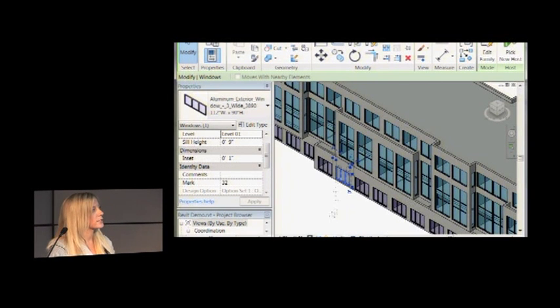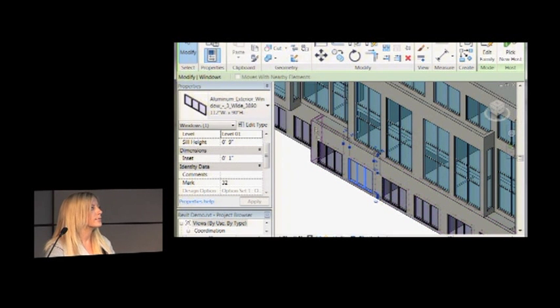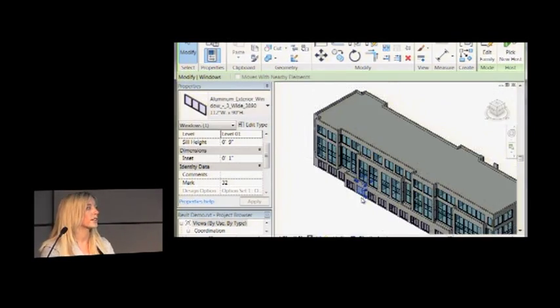But for those spaces, you basically just want to get rid of the room and make them external, because they're not actually an external space. They're a porch, they become a shading surface, or it's an atrium, and you don't need to have that defined as a room, because Revit will allow you to define it as a room, which is completely in opposition with the way that IES defines it. And for many of those openings, they sometimes will be filled in as windows, or they'll be filled in as a wall, but it will really depend on where it is, how big it is, and where it's positioned. So going in and cleaning those up and deleting rooms from any external spaces.